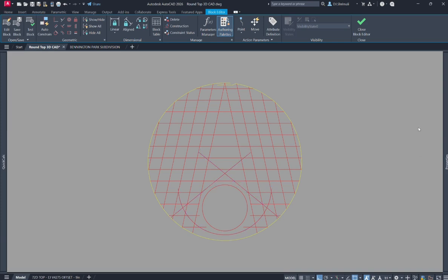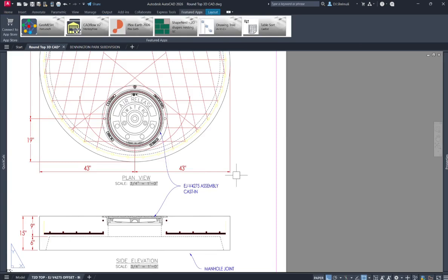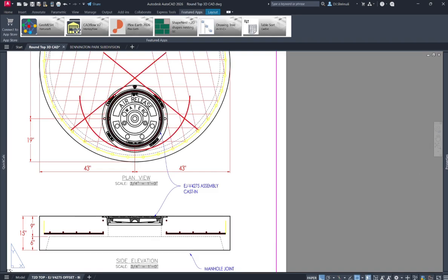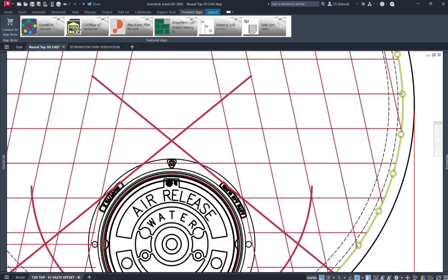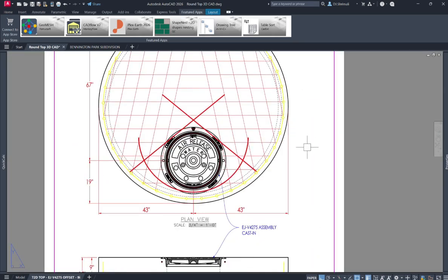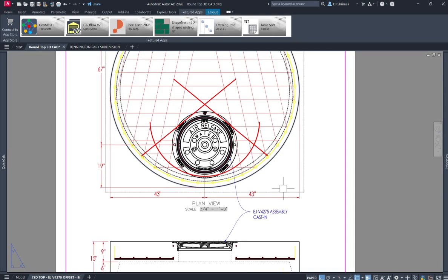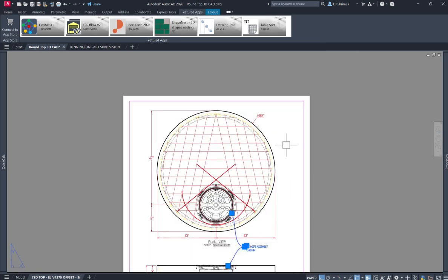So what I'm going to do is change the thickness of that polyline, the line width of that line, from the properties. As you can see, I changed the line width from the properties, so those lines look a little thicker. That's where the production guys can differentiate between the lines, or can see those 3 additional lines that we have to put to make the drawing clearer.